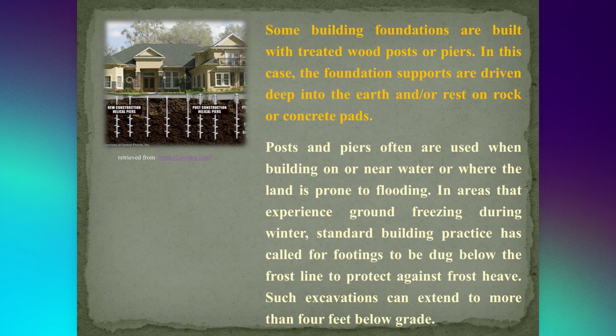Some building foundations are built with treated wood posts or piers. In this case, the foundation supports are driven deep into the earth and/or rest on rock or concrete pads. Posts and piers often are used when building on or near water or where the land is prone to flooding.